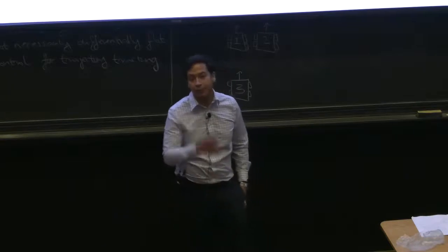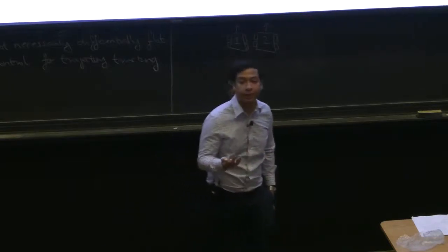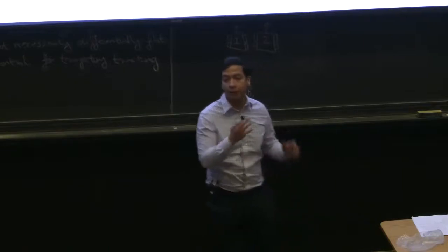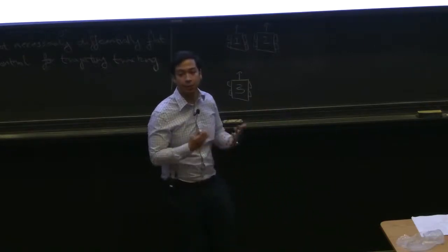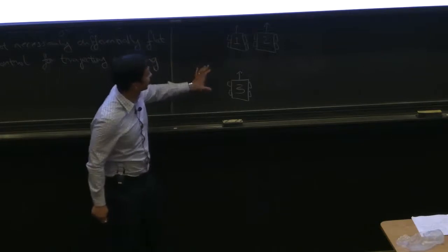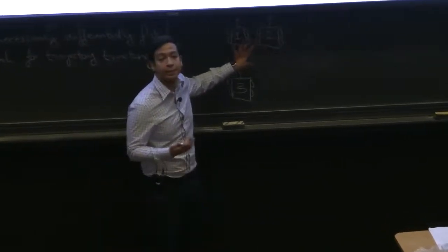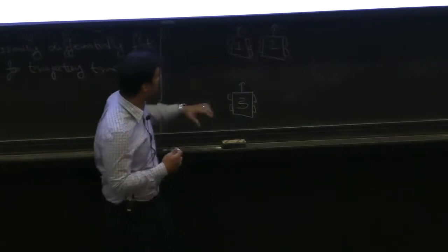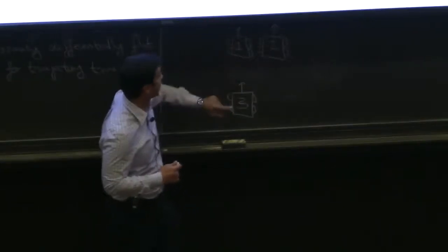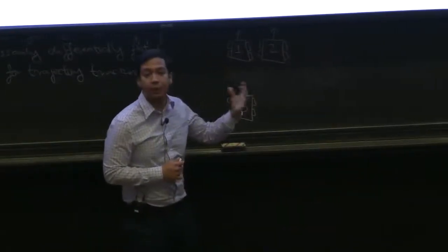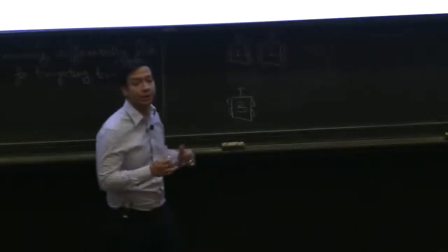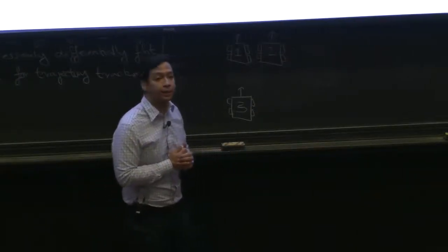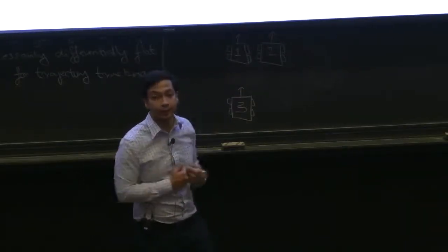Yeah, exactly. And so that's an argument for not using random sampling, or an argument for not using Euclidean distance as your notion of distance. So there are ways to modify the notion of distance to capture the dynamics of your system. So something that says 3 is closer to 1 than 2 is to 1. I won't go into the details of how you define these, but the main point is that Euclidean distance is not necessarily the correct choice of distance when we're growing the RRT.